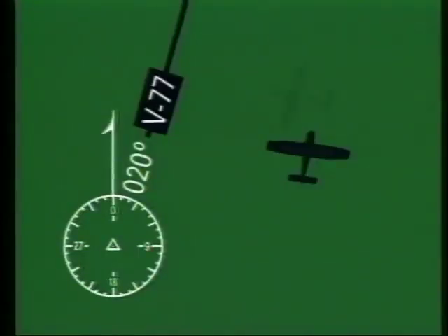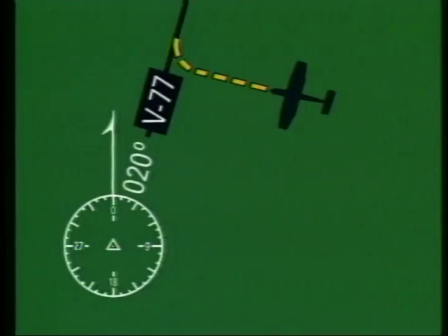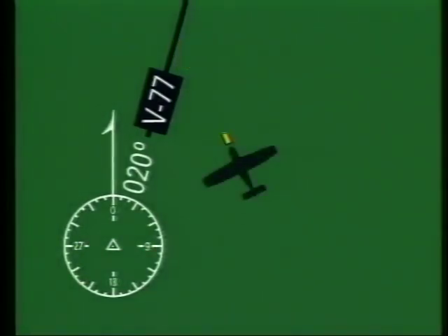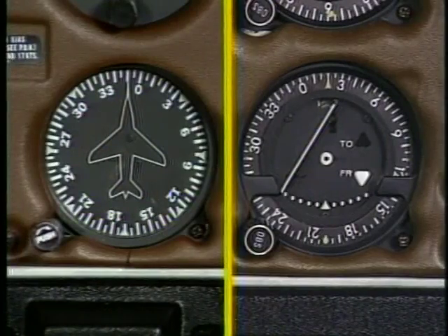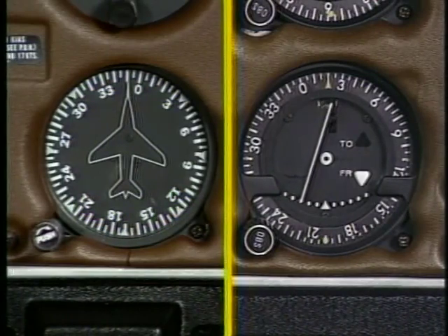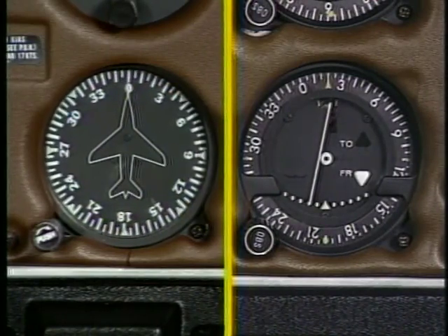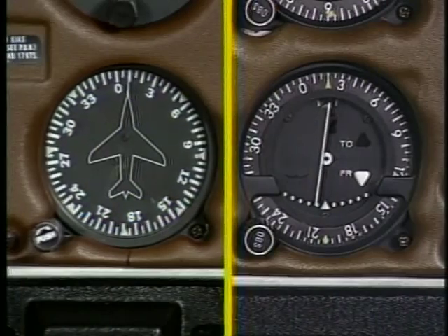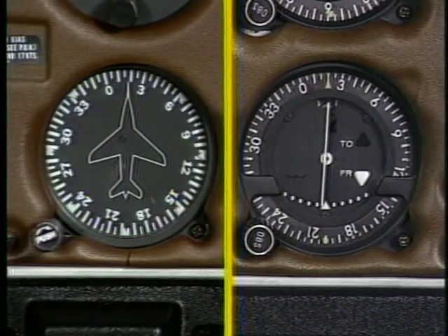One possibility is to fly a 90-degree intercept to the 020 degree radial. In this case, you need to anticipate your turn onto the airway, since a 90-degree standard rate turn takes 30 seconds. Another choice is to intercept the radial at a smaller angle. For example, a 30-degree angle is commonly used for en route operations. For this intercept angle, you must maintain a heading of 350. As you approach the radial, the CDI helps you anticipate your turn onto the course. At standard rate, the 30-degree turn will take only 10 seconds, so the amount of lead is relatively small.